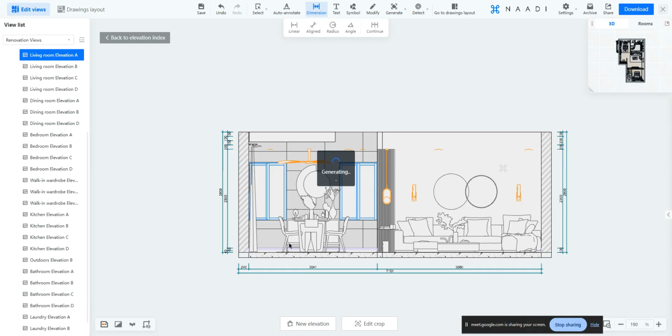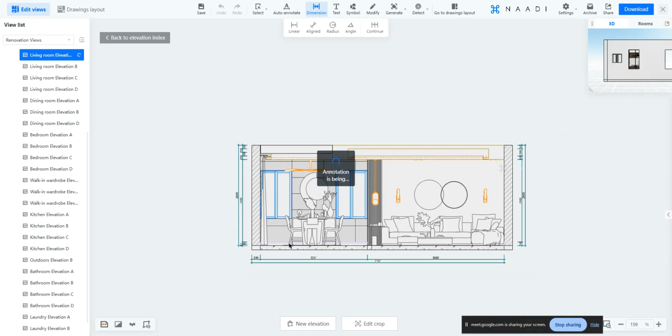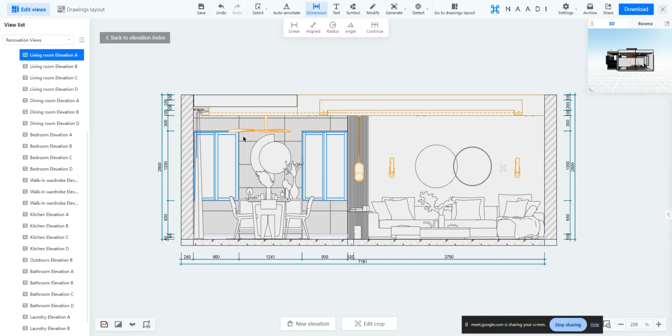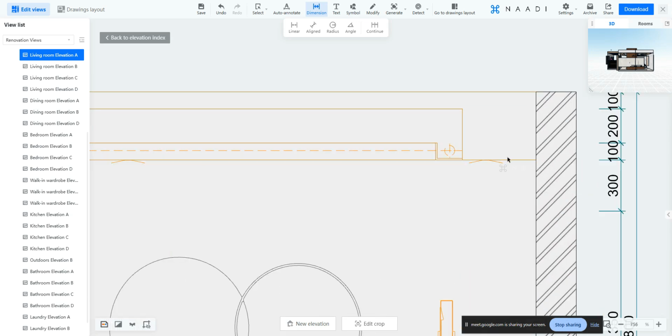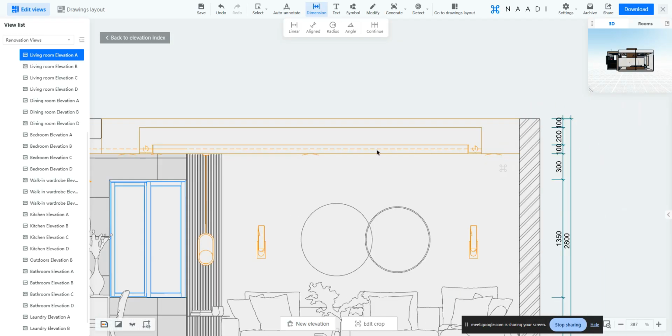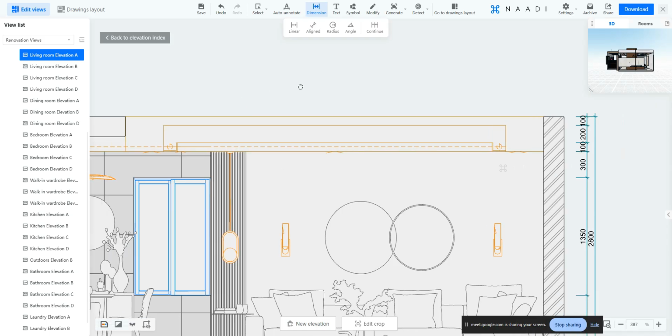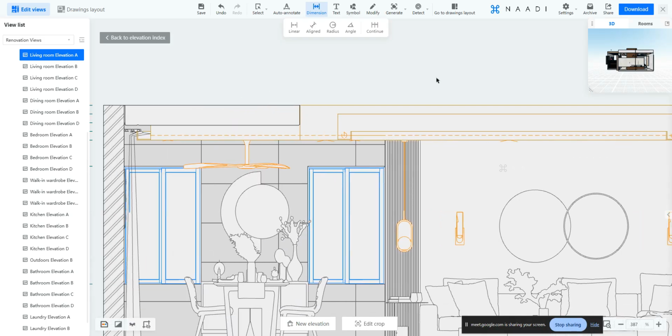So now we are able to understand how that elevation boundary boxes impact the extent of your elevation here. Can you see? So now I could see the dining wall here, the dining components and everything to the point. And most importantly, can you see here? Your false ceiling will be precisely notified, and here you will see the extrusion, the cove, the strip light position. This is the strip light position in section, and this dotted line represents the strip light position in that curve region, and everything is on point here.